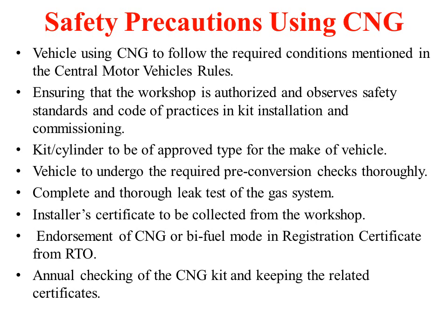Next, whoever fits the CNG to vehicles, that workshop should be authorized and observe safety standards and codes of practice in kit installation and commissioning. Whatever kit and cylinder are being fitted to the vehicle should be approved for that particular vehicle, or approved by the concerned authorities. Before fitting the CNG kit, the vehicle should undergo the required pre-conversion checks thoroughly, and thorough testing should be done once the CNG has been fitted.